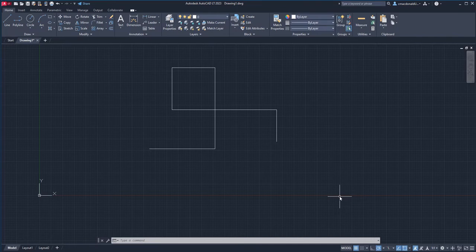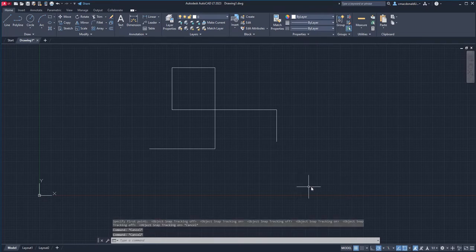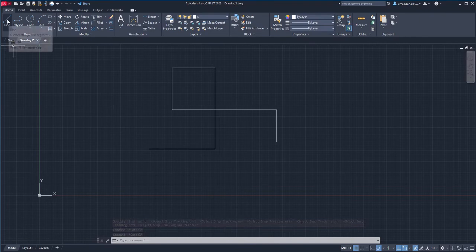The dynamic input tool can be reached by doing the thing we did before and bringing up the tooltips by hitting F12. As you might recall, once you have your line selected, left click, you can access the tooltip by hitting F12, which essentially serves the same purpose as dynamic input. Now, for those of you who prefer not to use F12, you should also be able to access dynamic input on your status bar here.